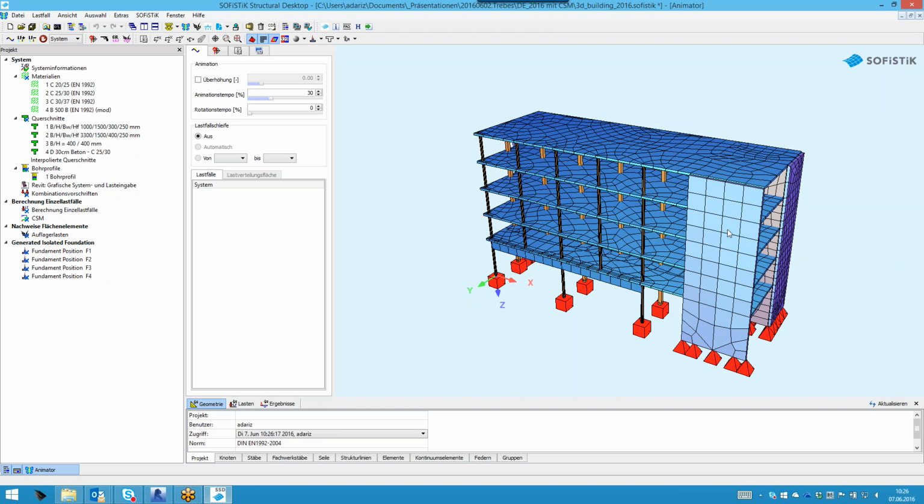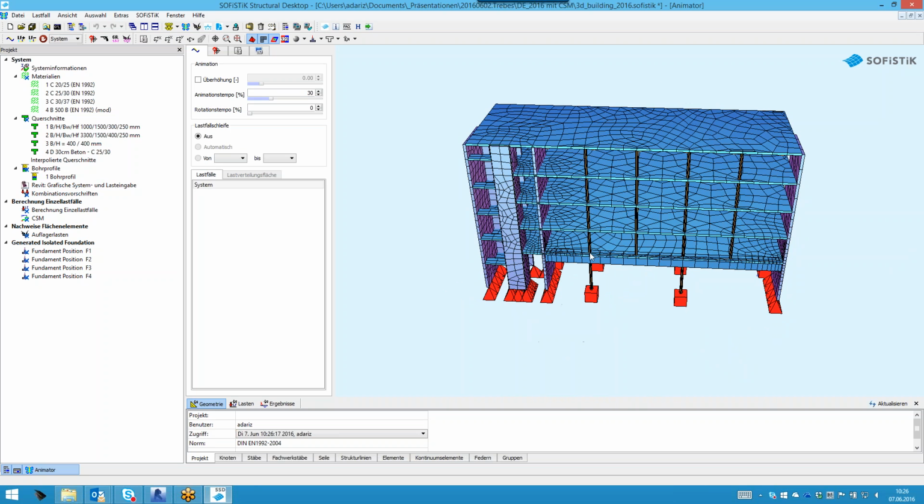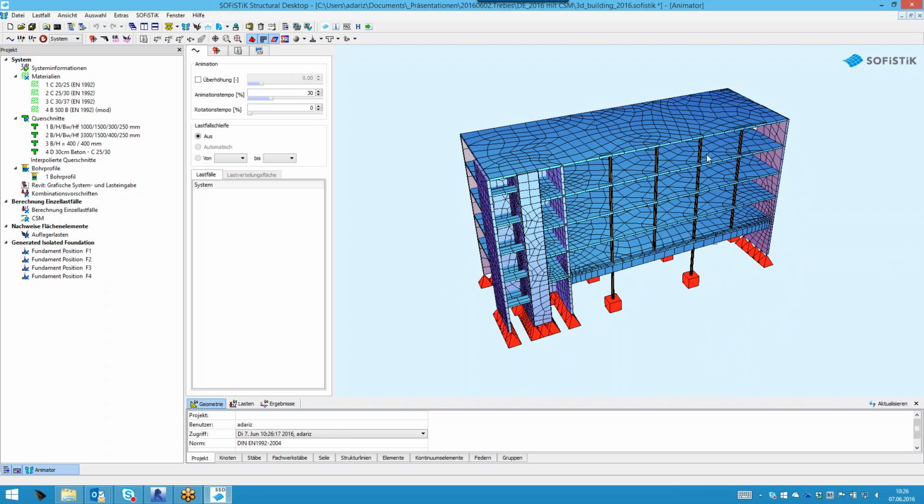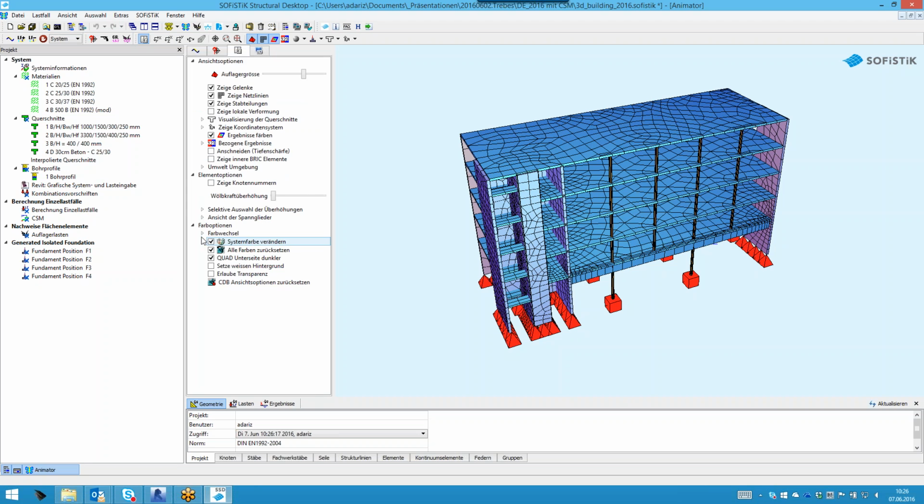You see we have meshed all the elements. We have created also some intersections between some elements like columns and slabs and so on. So the meshing is very good here. We have the possibility to also represent some different groups, because we can already assign groups in Revit, which is quite important for construction stage manager calculations, or maybe also for post-processing if you'd like to show results only for certain groups. And you see now a view where the groups are represented in different colors. So this is already possible inside of Revit.